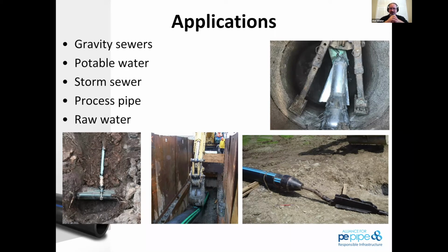You can also use the pre-chlorinated pipe bursting application to make sure that it's sealed and disinfected on the inside. Fire water applications, Yulia, thank you again for the question. It's a similar process as we go through. If that fire water needs to be NSF or properly disinfected before putting it back into application, then you'd probably want to look to a pre-chlorinated pipe bursting or static pipe bursting rig itself.